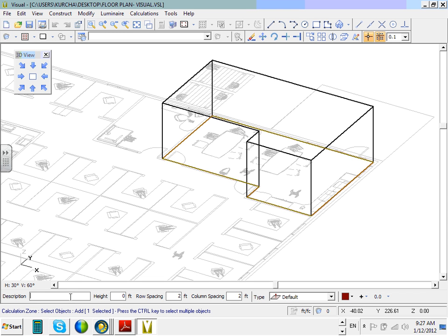So now, while it's red, go at the bottom and assign. Everybody can still see the red, guys. Click on the bottom of this and assign it. This will be calculation zone for which room? Room 119. Make sure the model that you built and the calculation zone match in names. So it's going to be room 119. Every time I see a calculation zone, guys, room 119, it will tell me that these calculation numbers are for the lunchroom. Doesn't take a rocket scientist. Okay, everybody got the lunchroom 119?